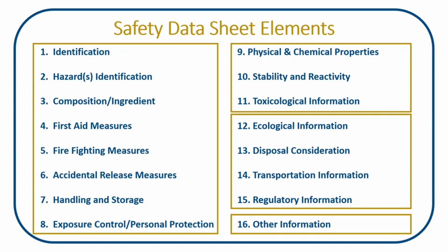The final 4 sections in the safety data sheet, sections 12 through 15, are included to be consistent with GHS standards. These include ecological information like ecotoxicity, persistence and degradability of the material, and the potential for the material to be bioaccumulative and mobile in soil. Particular disposal considerations include descriptions of waste residues and information on the safe handling and methods of disposal of the material, and it also includes information on the disposal of contaminated packaging.